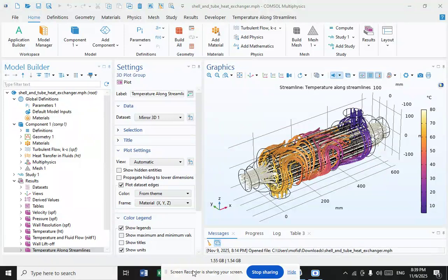A third and important difference is that plate exchangers employ more countercurrent flow rather than cross current flow, which allows lower approach temperature differences, high temperature changes, and increased efficiency.